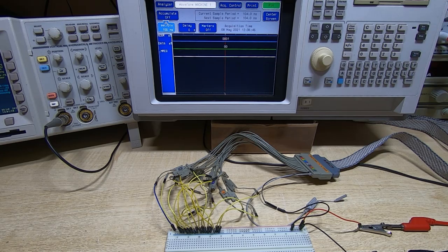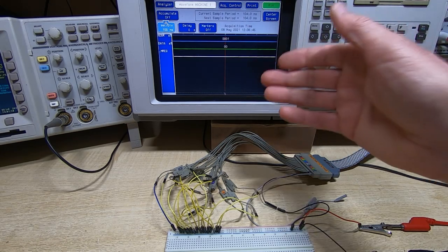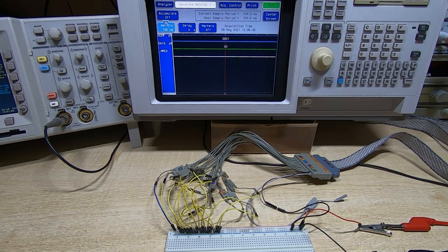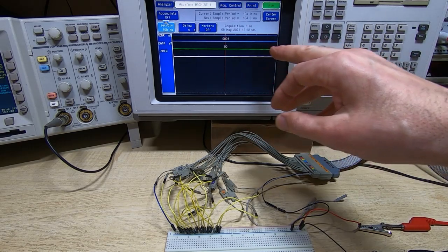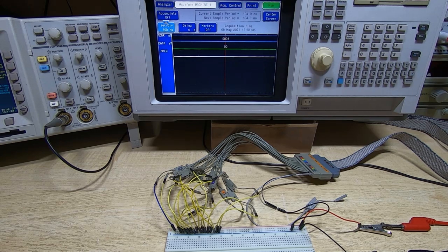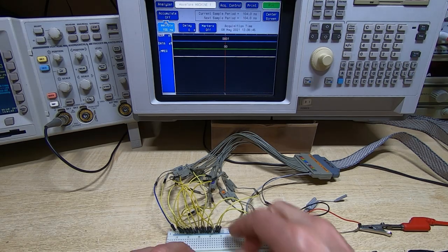So for example, if you're reverse engineering firmware, you're probably more interested in the actual values, or what the bus values represent, rather than the signal levels themselves. So in this case what I'm going to do is swap over the plus and minus signals. I'm going to move all the input bits that are currently connected to ground to 5 volts, and I'm going to move bit 0 to ground, so it will effectively invert this data, which is what you would see if you were using an inverted bus. I'll just move all these across.